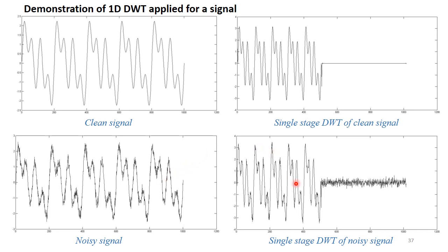For that, wavelet is applied. So one stage again. So this is the representation we are going to get, right? Now make a comparison of these two concepts: clean one stage wavelet, noisy one stage wavelet realization. What we can identify here is, this is the high frequency component, this is the low frequency component. In the high frequency component, there are no such high frequencies, so it is almost flat except at the very beginning part. Here noise is present, which I told is considered a high frequency component. So in the high frequency region of the wavelet transform, we are going to have this noisy component.